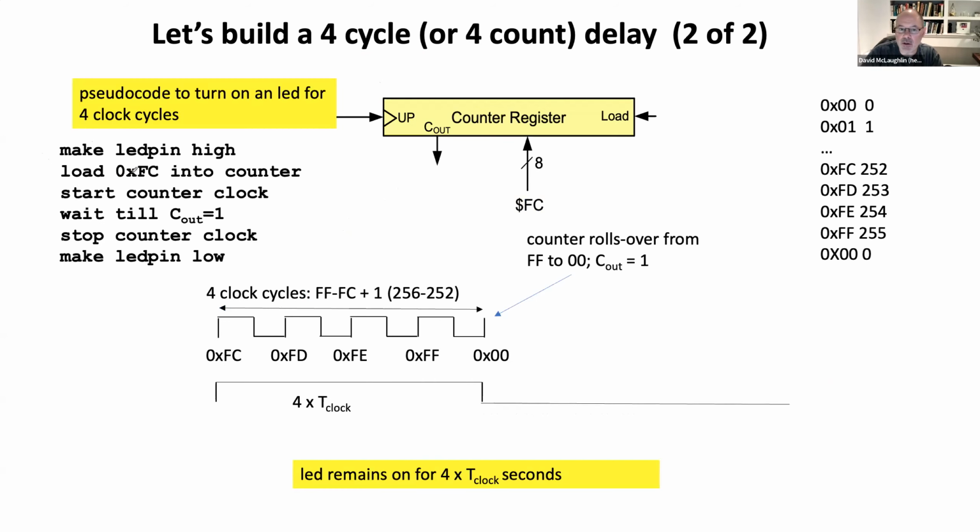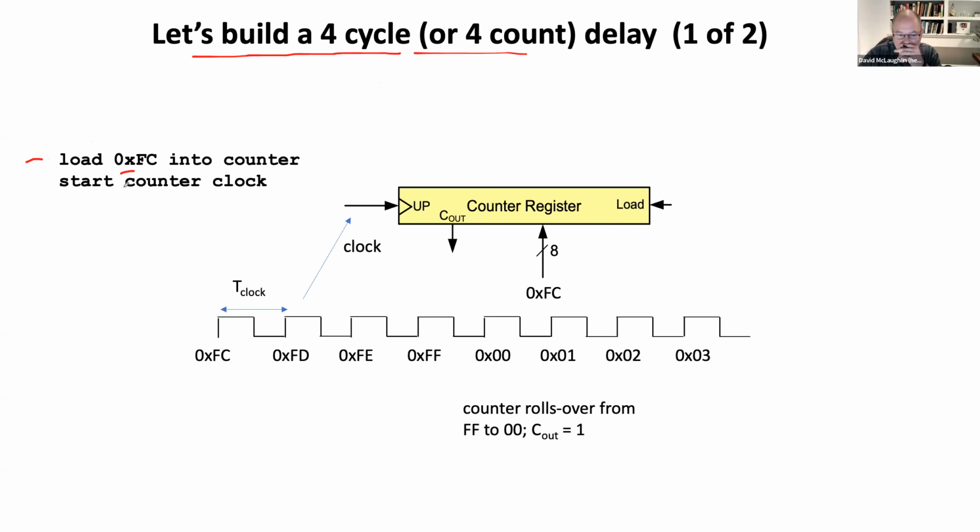0xFC into the counter. Now, why is that? Well, I want to start with that. I'm going to first load 0xFC very deliberately into the counter. Then I'm going to start the counter clock. So I load that value in, and then I tell it to start counting.